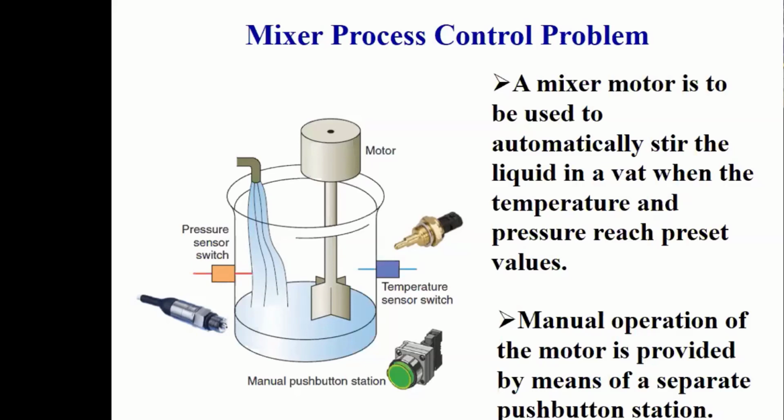So because this is a simple idea, that's the way it's presented. But you could have, for instance, a cover on that tank where no one and nothing can fall into the tank and be trapped, right? And for that, you'll have a cover, which will have another input, which will be a micro switch, that if the cover is open, that thing will not turn on, right? So that could be another enhancement.